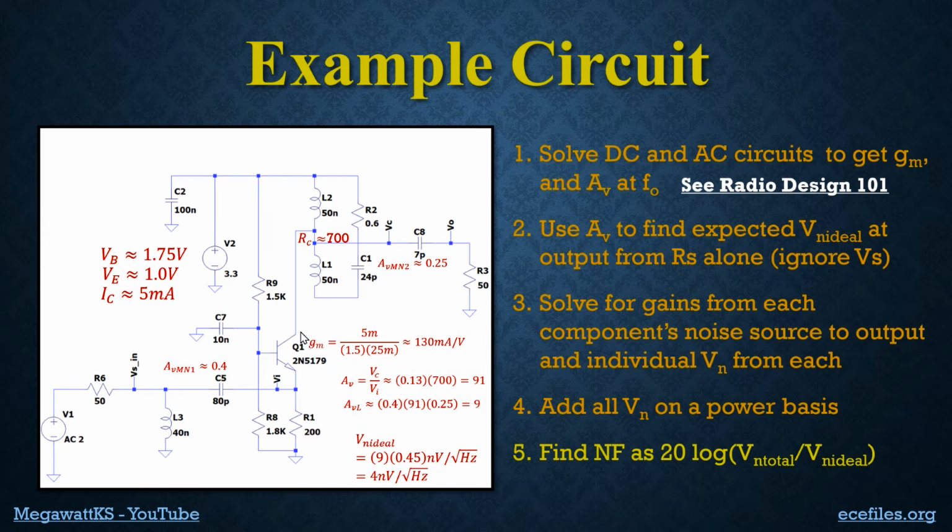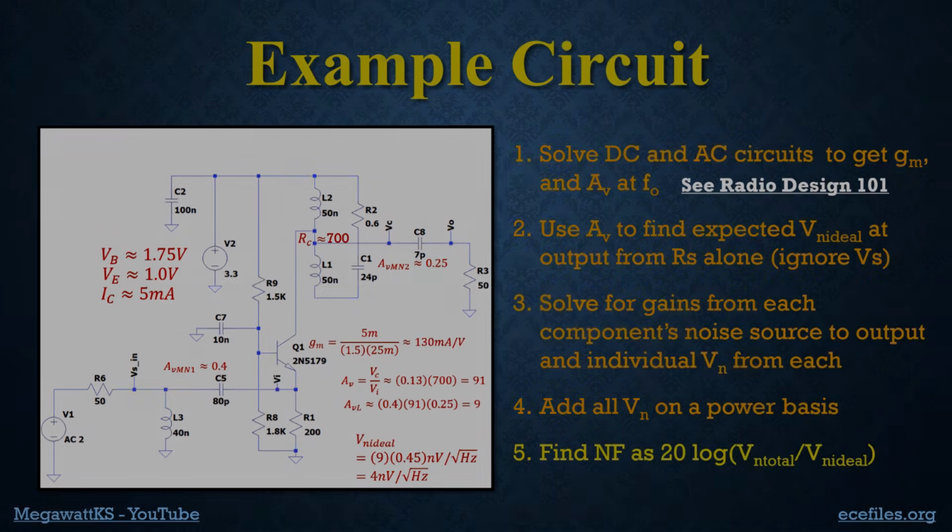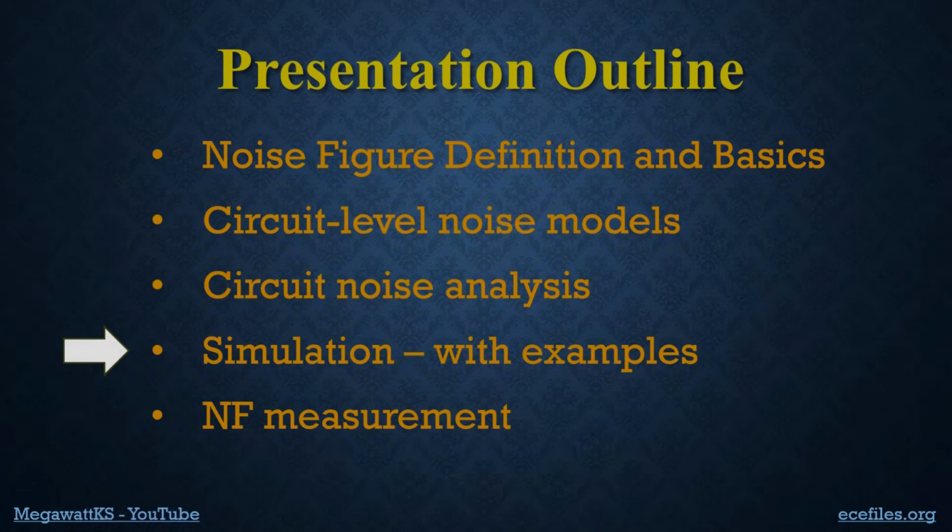So the noise current in this transistor from collector to emitter is going to be a dominant factor in the total output noise. That's the conclusion from all of that. So let's find out how big that's going to be, and more generally, let's find out if some of the simplifications, and the things that I said were not contributing noise at the output, are true.